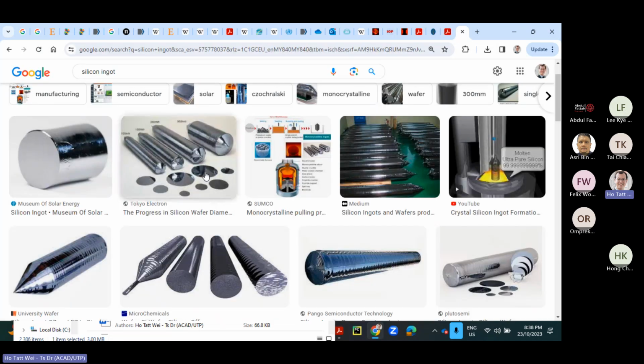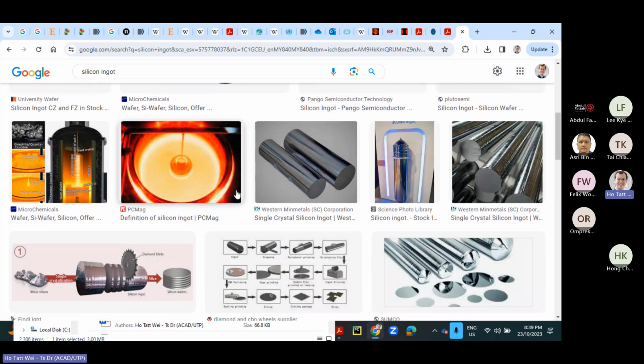So how is the chip made? There is a mask that is put on top of this, and then light is shone through the mask. And on the wafer, they put what we call photoresist. That is a chemical that when it's exposed to light, some of it will harden and some of it will not, right? So when it's exposed to light, there are certain regions that will be changed chemically and certain regions that are not. And then you will wash this with some kind of acid, and that acid will only be able to remove certain regions that have not been changed by the light, for instance. So that's the photolithography process. Okay. So you will do lithography on these, and within each wafer, there will be many, many different chips.